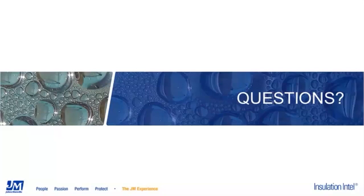If that becomes a concern, metal jacketing is readily available from JM with painted outer surfaces. So you can get a white painted aluminum jacketing, which will eliminate the drawback of the low emittance of the aluminum and how that could lead to high insulation thicknesses being required.